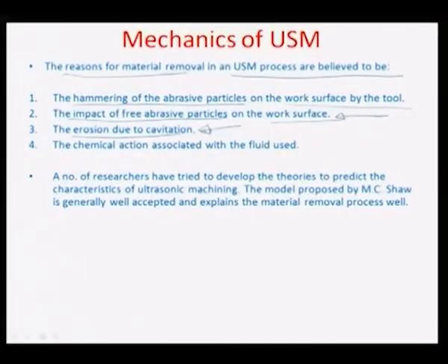So these bubbles actually get formed hugely at a certain frequency which is also very high, about 20 kilohertz in the USM process also, and the formation of the bubbles would definitely lead to some kind of pull forces, where the materials which are fractured using this brittle fracture theory on the surface would get pulled in by such a bubble, and it would promote fast dissolution of the debris which is formed because of the USM process. So therefore erosion of the material due to cavitation, or due to the formation of the bubbles in a USM, is also another principal mechanism of material removal.